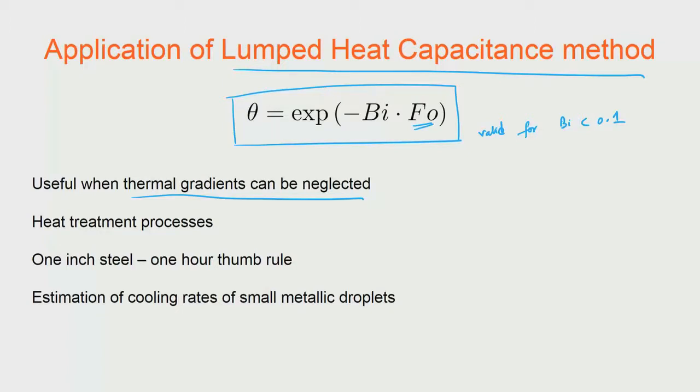Okay. Now, in heat treatment processes, we normally need to estimate how long it takes to heat up and cool down the materials, because that is time we need to give, which cannot be counted in the isothermal holding. Depending on the size, these durations can be significant. We can also estimate those durations using the lumped heat capacitance method, and in situations where those durations are large, it means that the sample is too large or the thermal conductivity is too poor. So, we must take these transient effects into account.